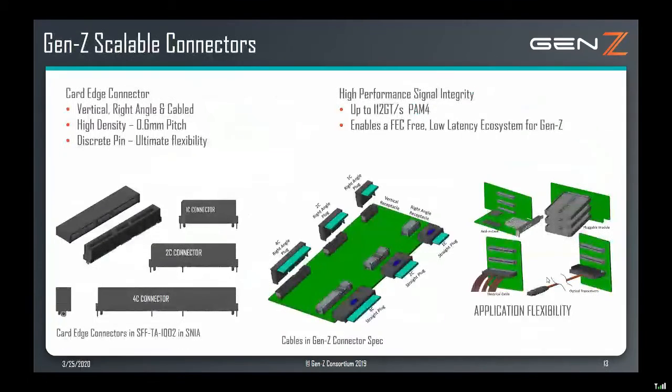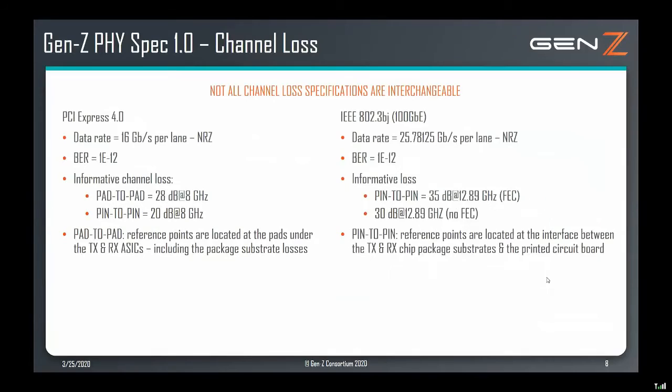Yeah, so I think the question is, what are the targeted use cases? And yes, I think what the person who asked the question was alluding to is, for PCIe, you would use it for things like FPGA connectivity and NVMe connectivity, whereas your switch-to-switch or bridge-to-switch connections would use the Ethernet PHY for most cases. The nice thing with Gen-Z is you get the flexibility. You can do whatever you want, but I think that's where we will see the industry going. Hopefully that answered the question.